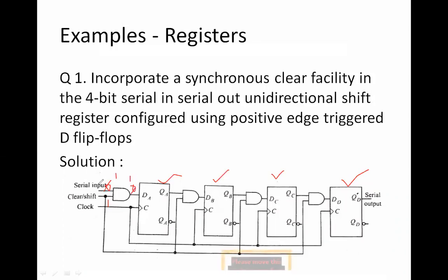So which means my data is actually getting transferred. It is not affecting just because I have a 1 here, right? So once I have the data here, with the next clock cycle, it moves here. And with the next clock cycle, it moves, and then to the final stage, it moves here. As we all know, with your D flip-flop, whatever the inputs are, the same thing occurs at the output side, right?